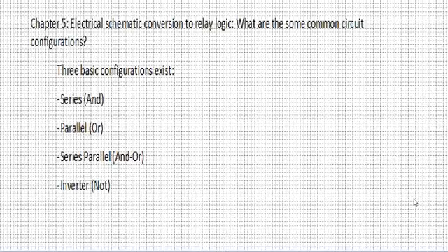Back, everyone. We are digging in with the ladder logic programming class, not without a foundation. We spoke at the beginning that it is necessary to understand relay logic before we do ladder logic. The reason is that at some point there will be a design for electromechanical function of a system before it can be converted into a fully automated system. And so relay logic is really the primitive way of doing ladder logic, and that's the reason we're studying this concept of relay logic.